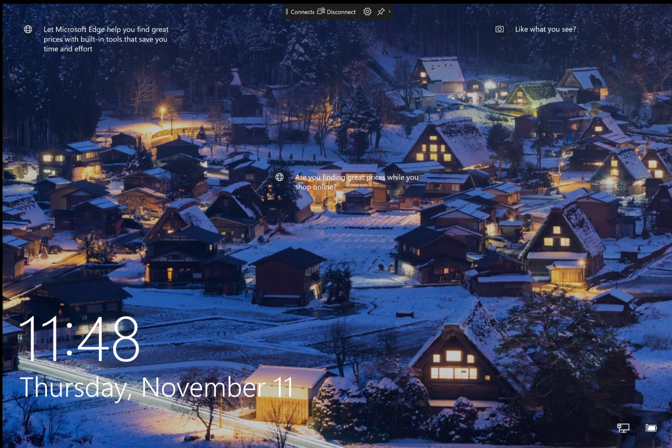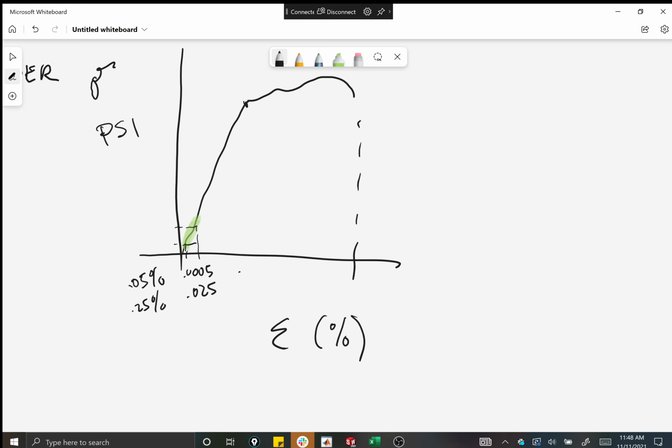But the point is that the stress is based on the area, and since the area is changing, we can't account for the area as it changes. Right, exactly. Now we could with a more complex computer program, but we say, okay, let's back off a little bit and simplify this. Let's just measure it at the very beginning. And also it has to be a standard.